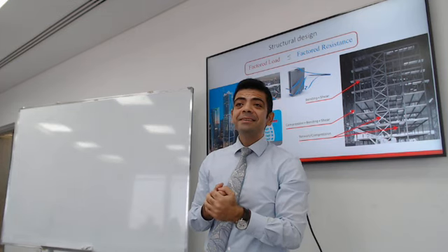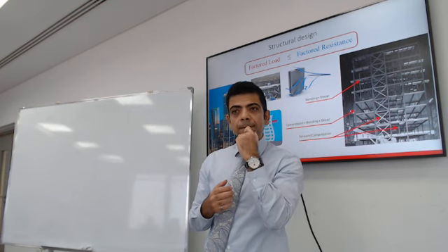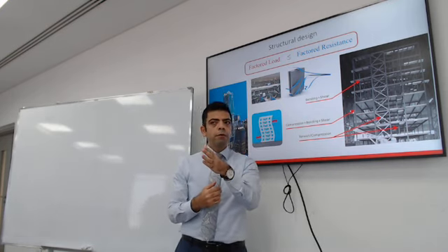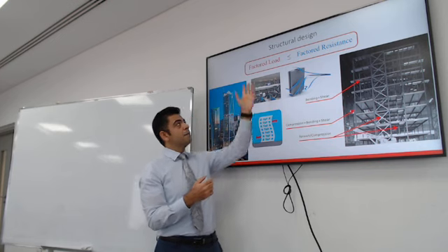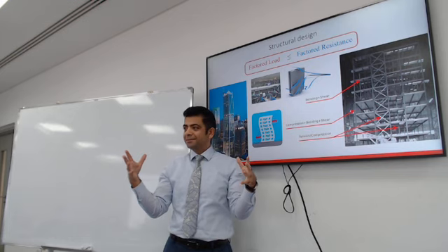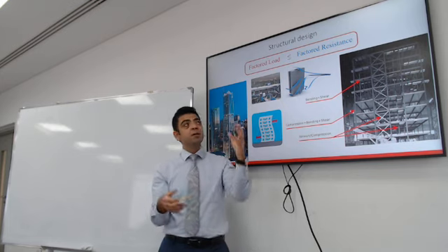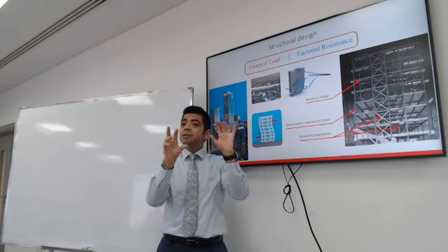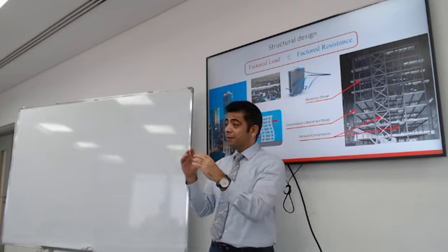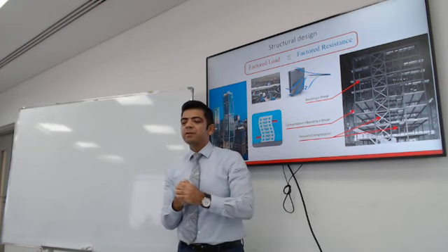It's the load that's actually applied on the device, and the factored resistance is how much load the beam can withstand, or your structural component can withstand. So you're on the right track. What I want to say is factored load is the actual load multiplied by a factor of safety. So these are the load combinations that we combine dead load and live load according to the code. Factored resistance is what the code tells us the capacity is, taking a factor of safety in the material strength. So we will see that in an example.